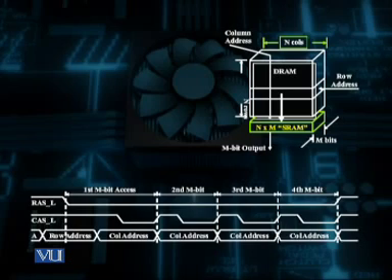This way we make use of only one row address select followed by n column address selects instead of a row address and a column address repeatedly, as in the case of standard dynamic RAM.